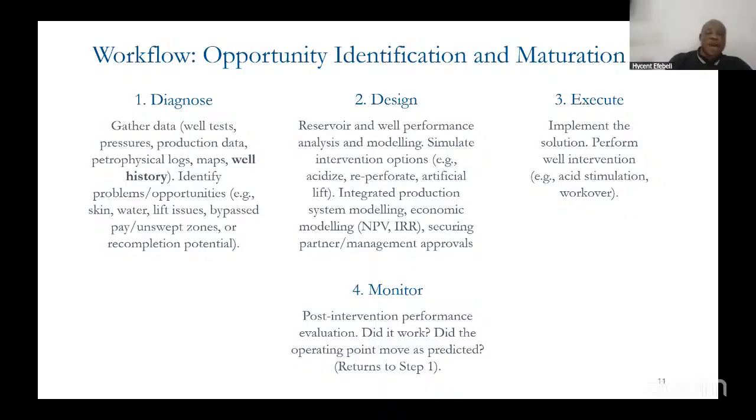When you are looking at the map, are the wells in a particular part of the structural map the high water producers, or are the wells at the crest? How did they perform? Did they produce water? Those are the things that you are looking at. So you are looking at well history. Well history, I made it bold. It is very important. When you are working, make sure you ask for well files, the digital well book. Know the history of the well.